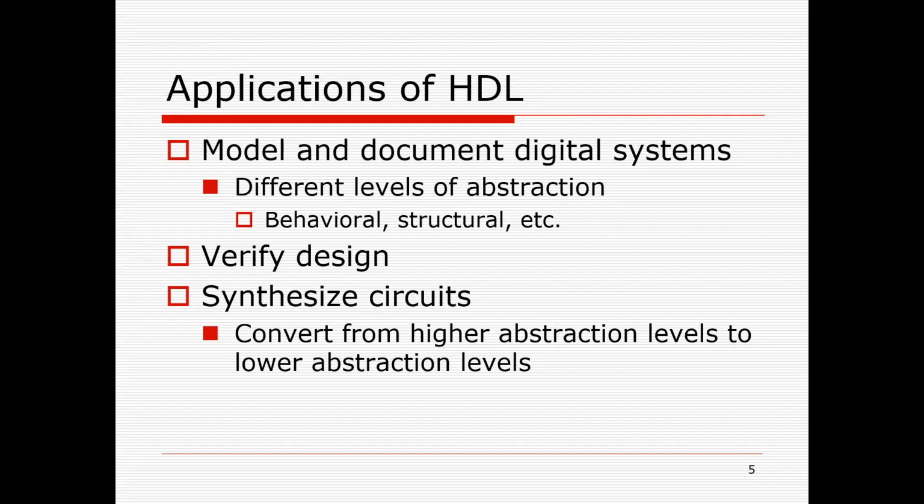Because at times when you are designing a digital system, you are at the top abstraction level, where you know the behavior of most components, but you know the structure of some, so you can add those structures. If for a particular block you know the data flow, you can add data flow. So you can combine anything. The first things we said are documentation and modeling. Then you can simulate it to verify whether it is behaving the way you want, checking input versus output, etc. And the third important thing is that you can synthesize the circuit. If your code is synthesizable, you can convert your VHDL code from a high abstraction level to a low abstraction level, which is a gated netlist.